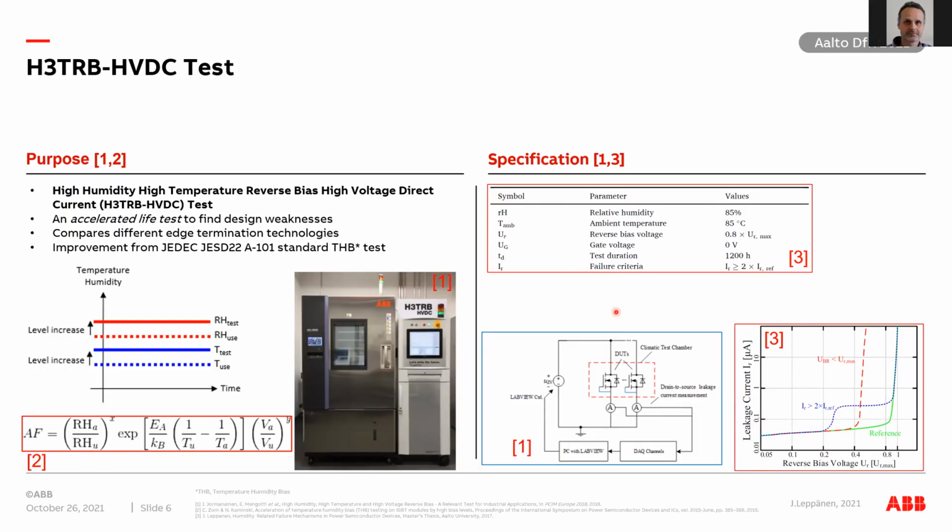Maybe, Jonas, I can ask a question on what students are thinking, just concerning the final measurements. Do you have some kind of recovery time after the test to drive out the moisture, or do you just ramp down the test and then make the curve tracer measurements immediately? Because at least in some 85 standards, there are criteria that you need to allow the sample to recover if you compare the initial test and the result after the testing. So how is that done in practice?